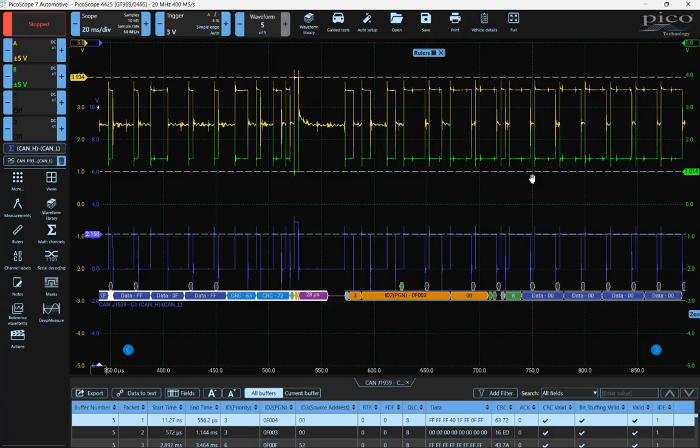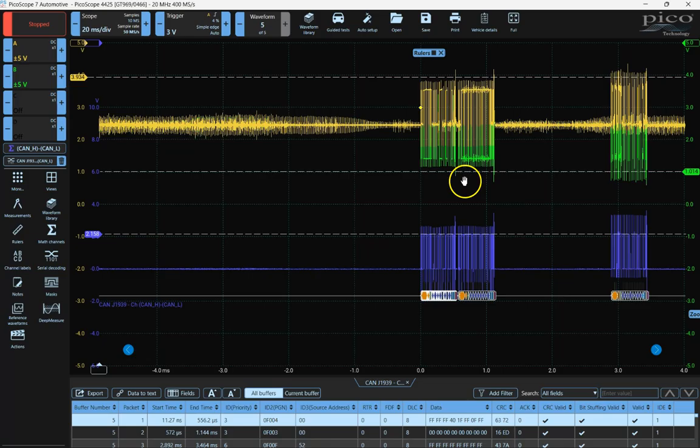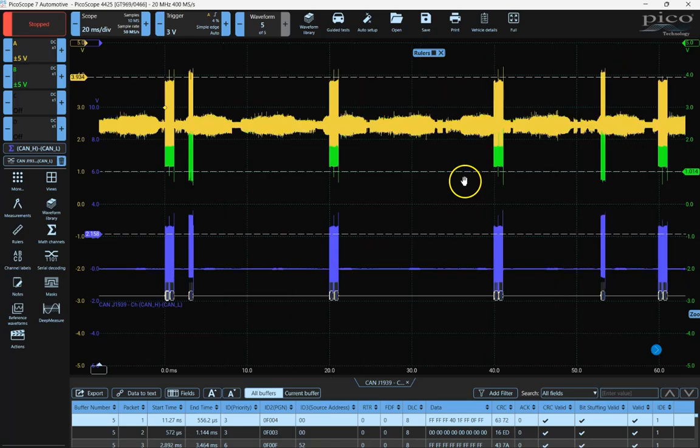But it's one thing that you can definitely pick out with the oscilloscope. Obviously, this short to ground scenario, you could probably find with a good multimeter if you took your time. When we start looking at the opens, your digital multimeter is not going to be of much use to you, as we'll see.